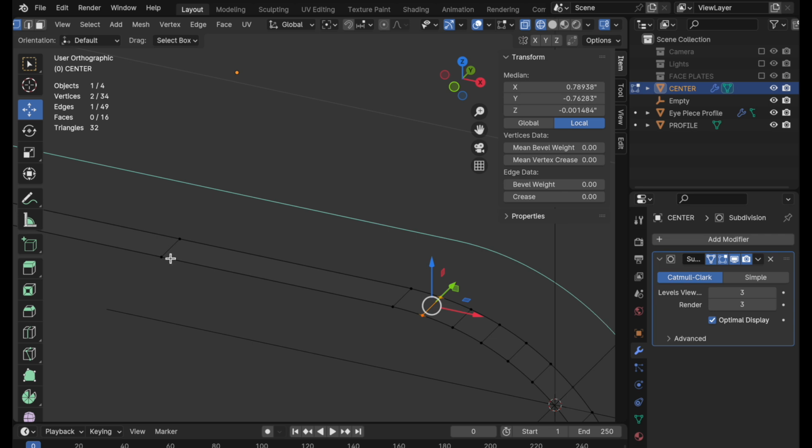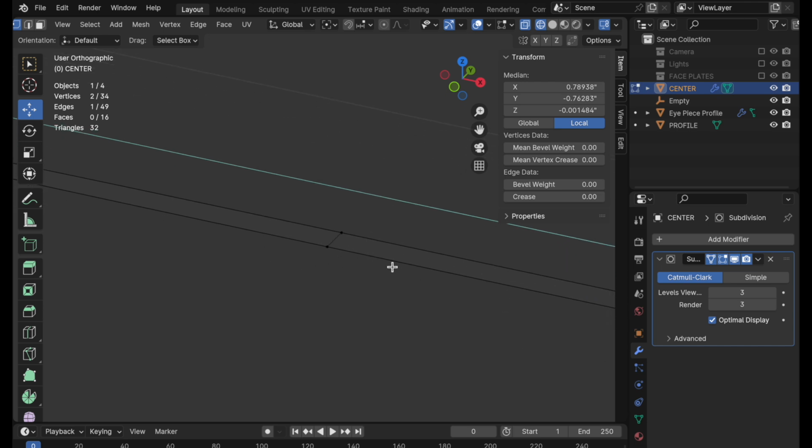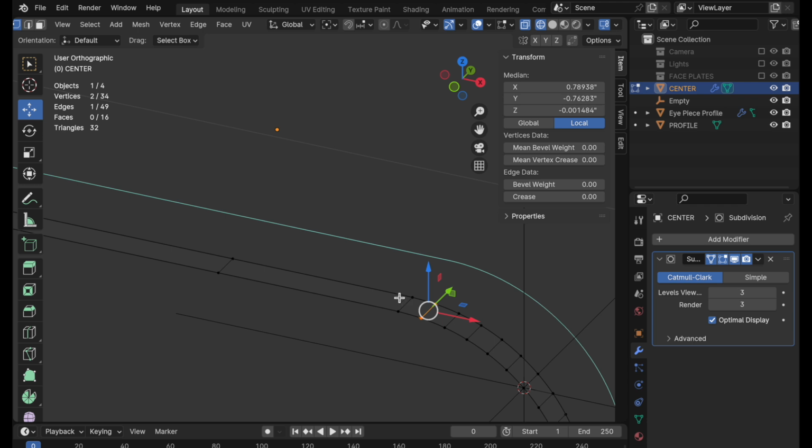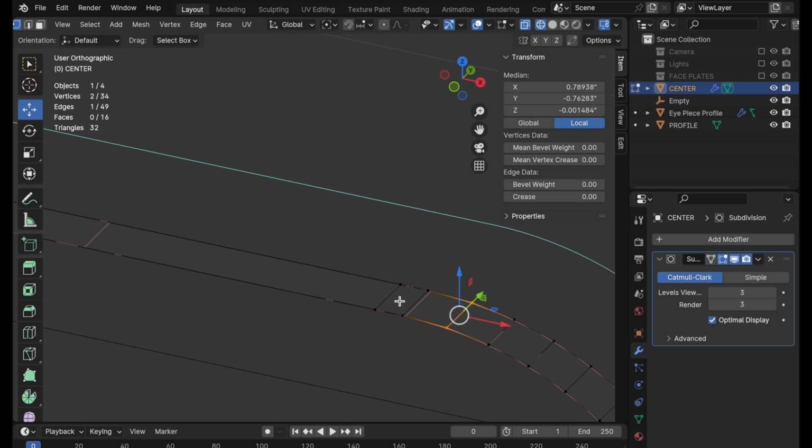And this is suddenly way over there. So what's going on? Well, because it's being subdivided and there's not another edge until way over here, the subdivision is blending across that surface. And I would really like this original edge to be right there. This is a boundary polygon, and it needs to stay right there so that we don't have any curve influence coming past that.